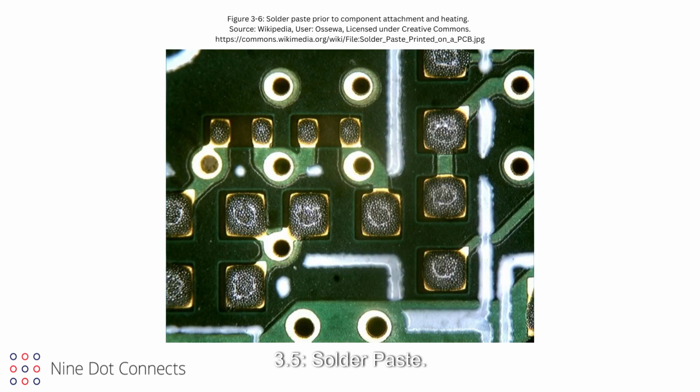3.5. Solder paste. Although solder paste is primarily used to provide the soldering material necessary to bond the component lead to the PCB landing, it is also an adhesive that can hold the parts in place prior to reflow. It is a viscous mixture of solder balls of various metals, flux, and volatiles that are activated under temperature.